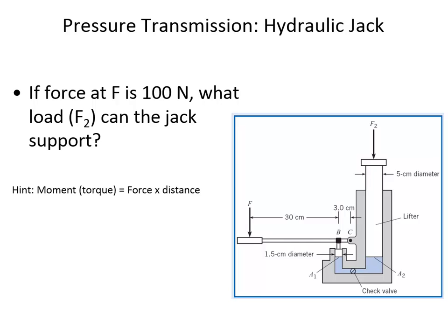And so this is just like with what happens with a crowbar. You know, if you've got a bar and you're trying to break open a safe door, you want a really long bar so you can grab the end of the bar and you're pulling on the bar, and then down at the safe it's just moving a few millimeters to gouge the metal before you can open up the safe. But the same thing is happening here, where you're amplifying the force. And so if you push down at F with 100 newtons, then that 100 newtons, it's going to be more than 100 newtons that's being applied over this area.